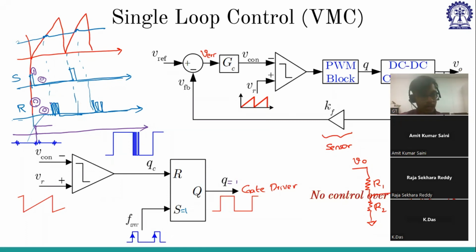And when you receive a reset of 1, here we are receiving a reset of 1 and set is 0. Set is 0, reset is 1 means it will get reset. When it got reset, now reset is changing to 0. In between we have reset value 0, but set is 0 and reset is 0, so it will retain the previous value.